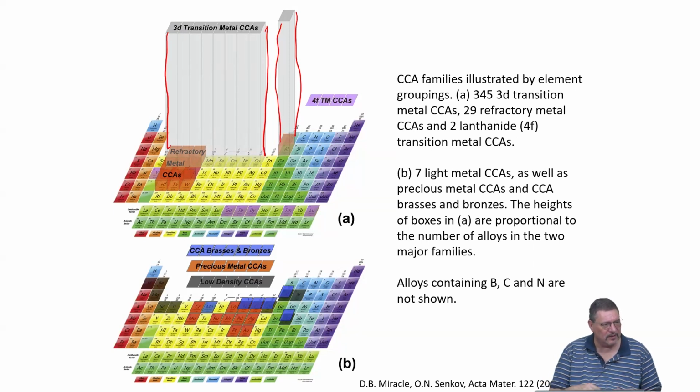And we discussed already that there are different conditions, relying on different properties, in terms of stabilizing complex solid solutions. And this mixing enthalpy as well as the difference in effective atomic radii in solution are the two most important, I think. And so the similarities in these properties between the different atoms and different atom pairs control whether you can easily make a solid solution or whether you will probably find formation of an intermetallic phase, which most of the time is to be avoided.